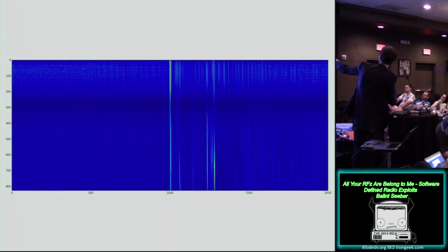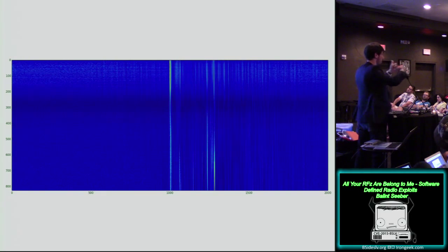And so this is offset by whatever, 60 samples, which translates into maybe microseconds worth. But this is actually showing you that you've got one strong signal coming in, and then maybe two other ones arriving, say, 5 and 7 microseconds later. So this is actually telling you how many reflections you've got coming in to your one point where you are.